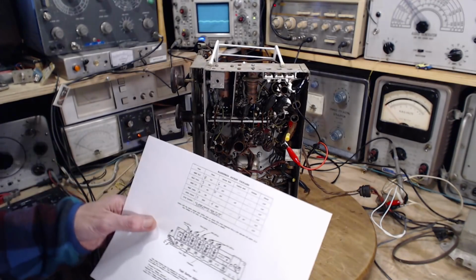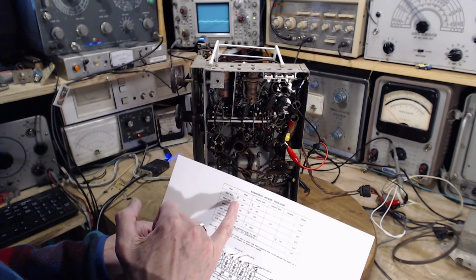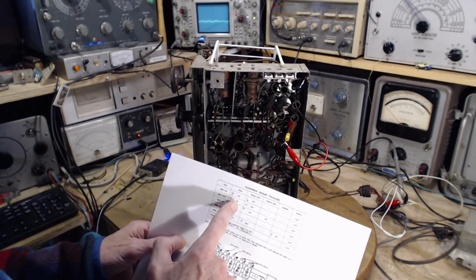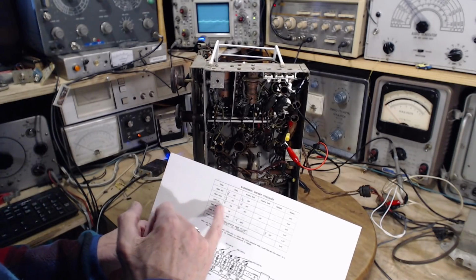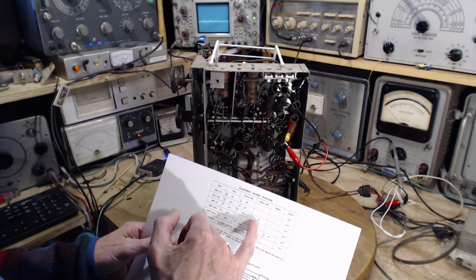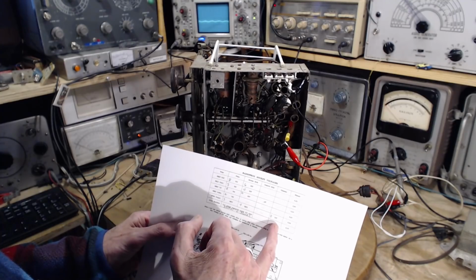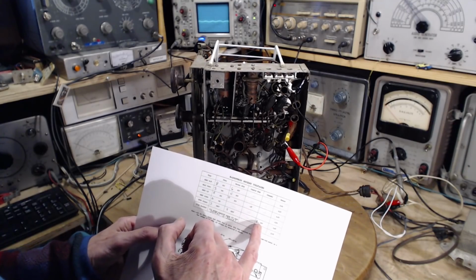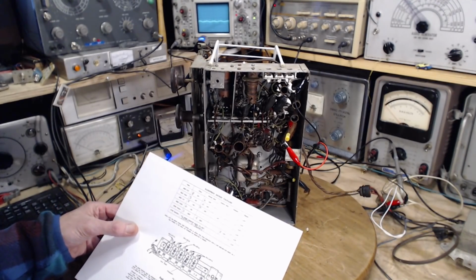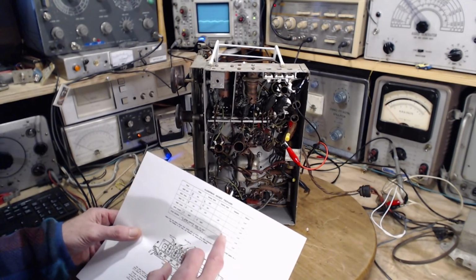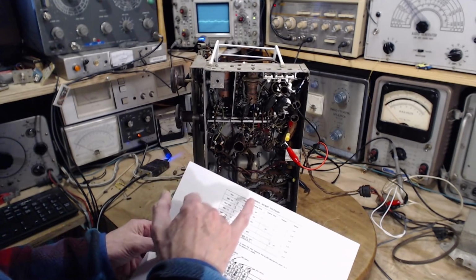Okay, so I printed out that voltage table, and I've taken the time to write down the pin numbers, because they're not on the table, which pin on each tube to test. Mostly it's plate and screen voltage we're interested in, but we're also interested in control grid, a little voltage there we may want to check. This is the one that I'm most interested in. This is 13 volts. This is a drop on the cathode resistor for the output tube, which is where I suspect problems lie. And we should also be checking the grid of the output tube, which I didn't mark on here. We'll worry about that when we get to it.